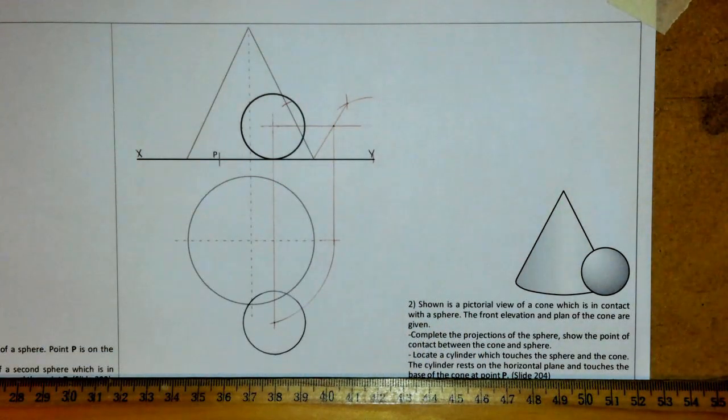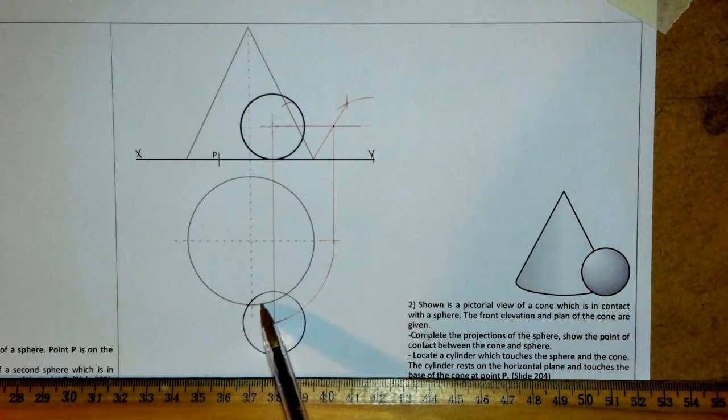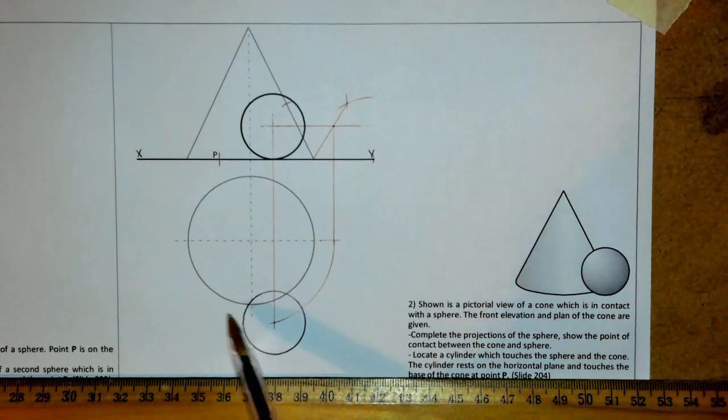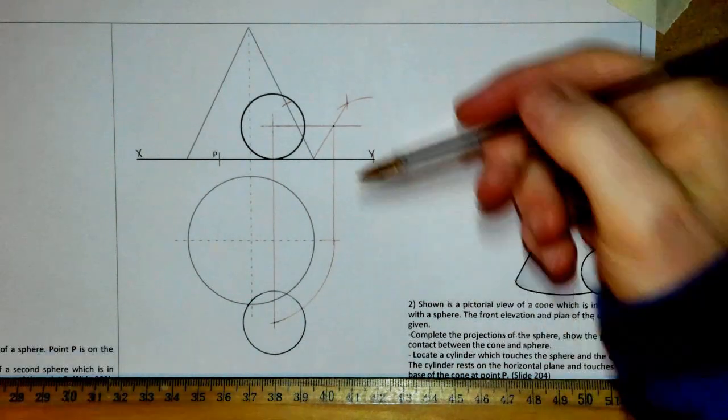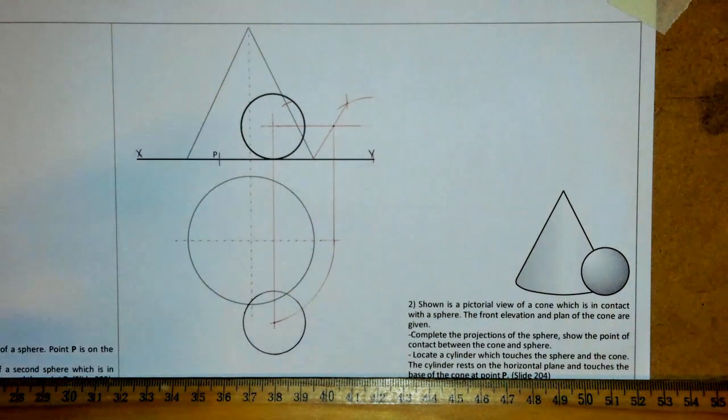And what we should have, guys, just in our plan view, because the sphere is overlapping the cone, is that there should be hidden detail, so it should be a hatched line. Okay, we found it in elevation, it was already given to us, but the next thing we actually have to do is find the points of contact. And we know the way to find the points of contact when a sphere is touching a cone is that the perpendicular from the center to the extreme generator should give you the points of contact.